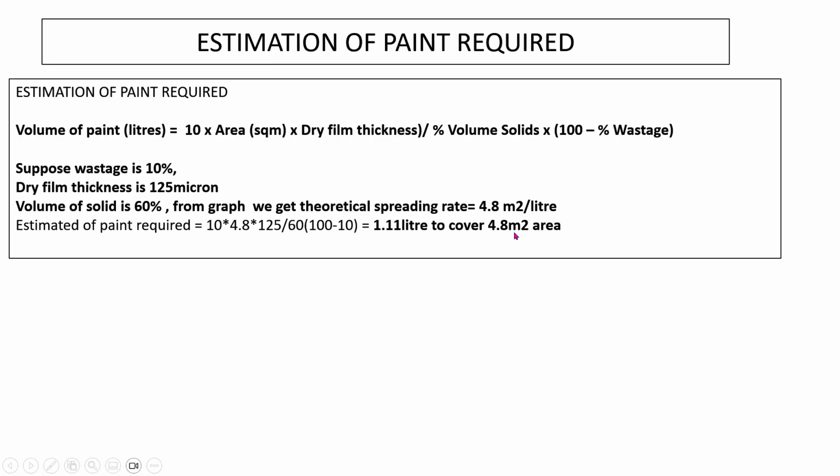Now the estimated paint required. From the graph you can calculate, as well as from the formula: 4.8 into 125 divided by 60 percentage volume solids, with 10% wastage.